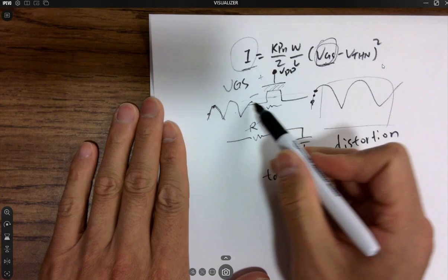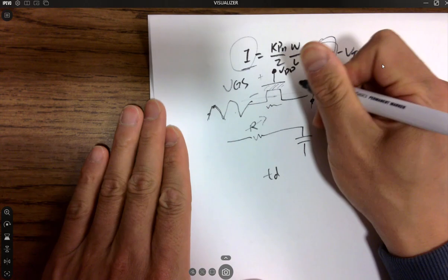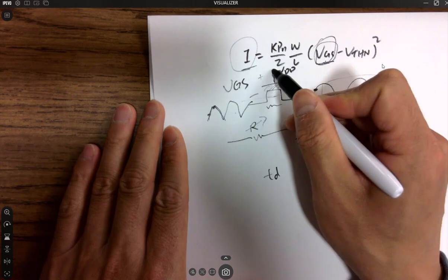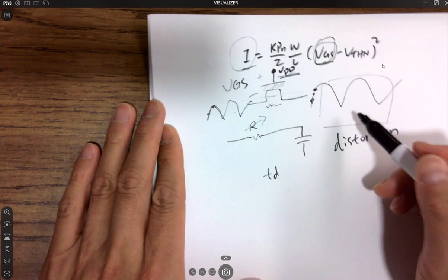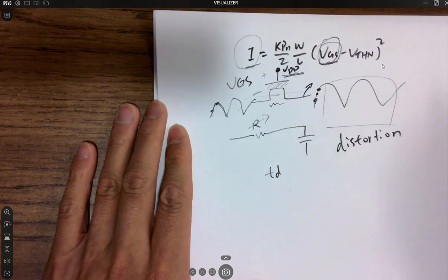So in that case, a very simple transmission gate, also called a pass gate, just using transistors, right? And you tie this to VDD with a constant voltage, will give you a distortion to the sampled voltage on the other side.